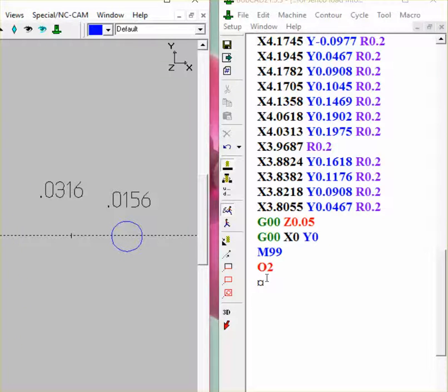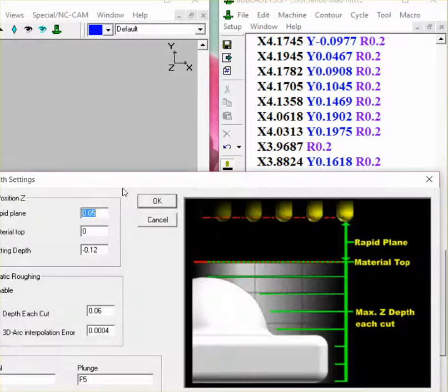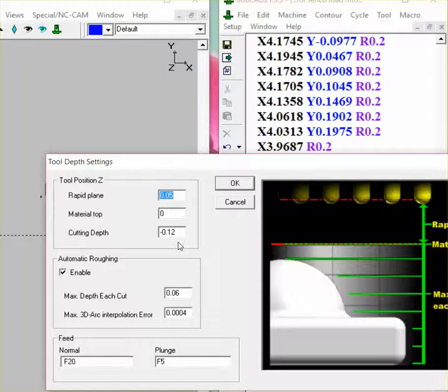This time you have your tool bit changed. Now that's a different size bit, so you can't run a 15 thousandths bit that deep. I like to do about an equal amount on that bit, say 15 thousandths per pass, and it'll do all the math, calculate it all out. And I want to cut back my feed because it is a 15 thousandths bit. Cut back and use these numbers here to keep from having tool breakage.